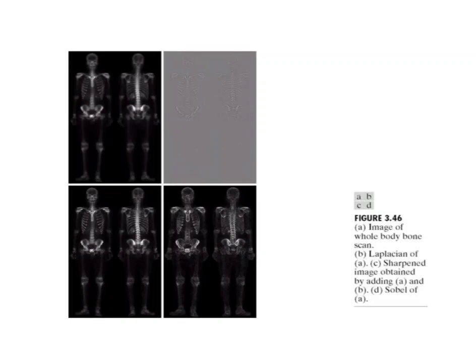The response of the gradient to noise and fine detail is lower than the Laplacian, and can be lowered further by smoothing the gradient with an averaging filter. The idea then is to smooth the gradient and multiply it by the Laplacian image. In this context, we may view the smooth gradient as a masked image.